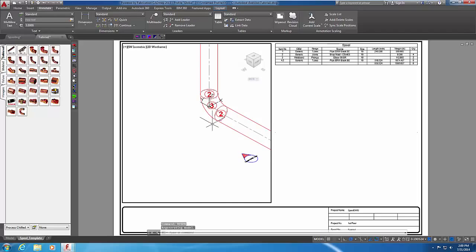Use the Move Object Text in Viewport Only command or Move Text VP located on the CADmep toolbar to move the item number tags to the left side of the pipe. The item number tags are more clearly seen. The items with an item number of 2 are welded joints. The pipe elbow has an ID of 3.